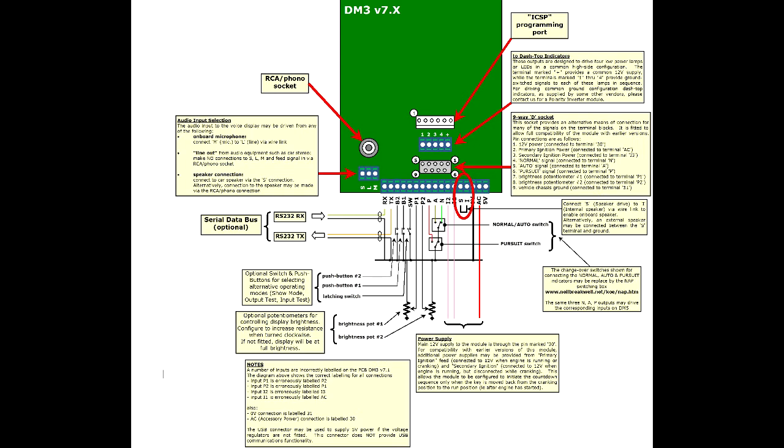You'll see also from this diagram that we have a short wire link between the pins marked S and I on the terminal blocks. That's to connect the speaker drive output, which is on pin S, back to the onboard speaker input, which is pin I, to enable use of the onboard speaker.